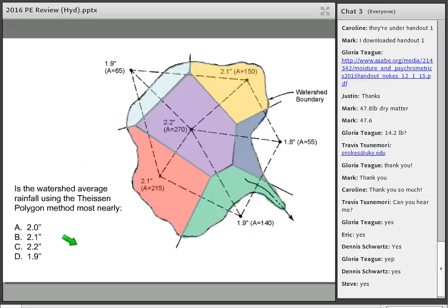So then you've got another concept that actually you're going to find we use a time or two more as we work through some of the hydrologic processes, which is areal weighting. In other words, weighting by relative areas of these portions of the watershed. So what we're going to do is take the rain gauge reading, multiply by its area of the watershed that is closest to it, sum all those products up and divide by the sum of the areas of the watershed, and you end up with an area-weighted average rainfall. Let's look at the actual calculation of that.